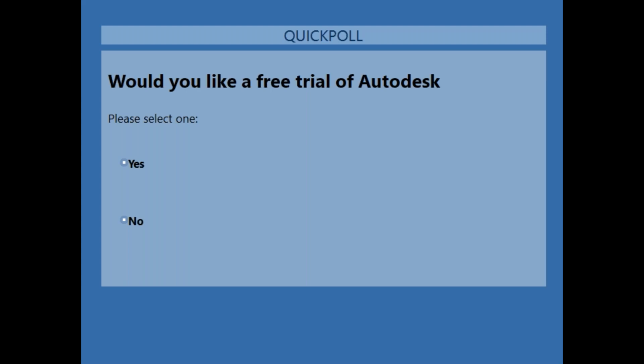In the meantime, let's see if there are any questions we can answer live here. I think there's a good question here, Rachel, from Betty. Do we have to load the classification template every time we do a takeoff? And the answer is no. If you're using the templates that we went over in the beginning, all the settings will be automatically applied. That includes the takeoff packages and the classifications, the measurement systems, and all those definitions for those takeoff types. So that would have an automatic application to projects going forward using that template.